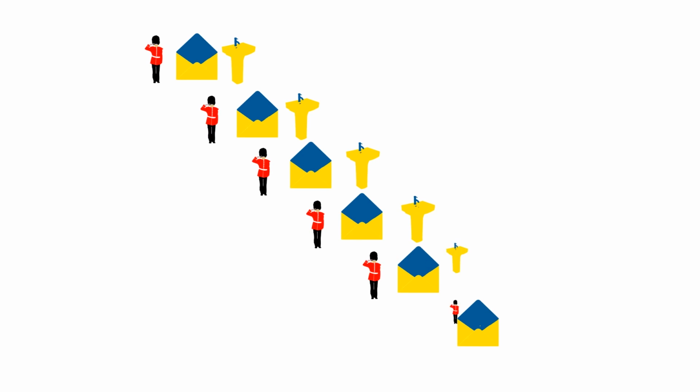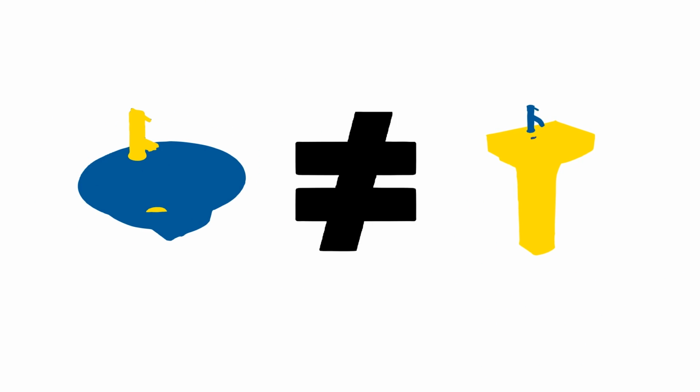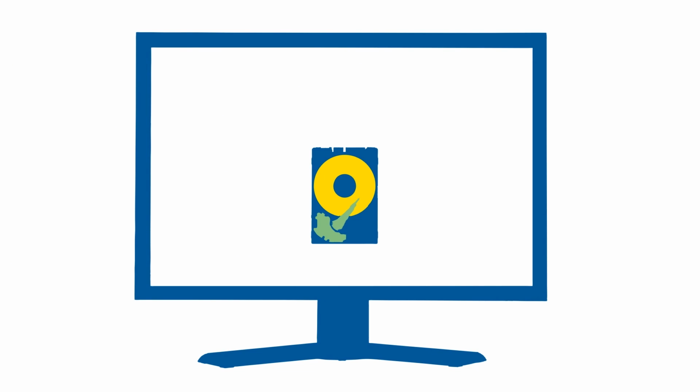With the binary chunks, we can determine whether a packet was received correctly. This is done by comparing the sync component of each chunk with a predetermined sync pattern. After validating the sync, the message data is extracted from the now known good packet. Finally, we can reconstruct the data back to its original form and display it in our application. Now let's take a look at all of that theory in action.